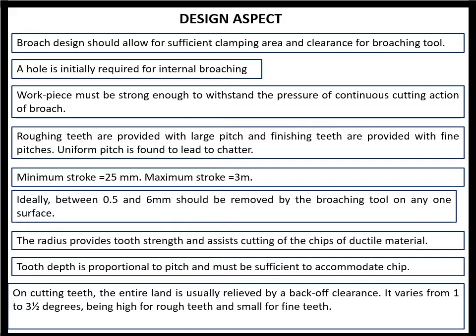The radius which is provided at the gullet spaces gives each tooth strength and also assists cutting of the chips of ductile material, and the gullet space accommodates the chip when it is removed from the workpiece surfaces. The tooth depth is always kept proportional to the pitch, and it must be sufficient to accommodate the chip.